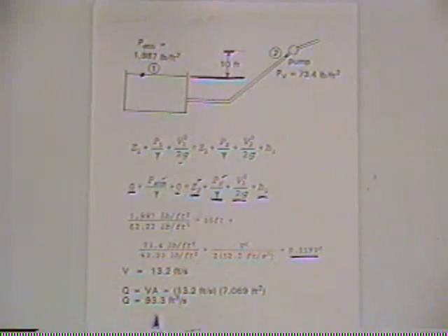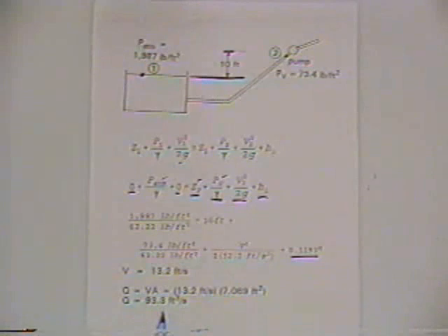So as long as we've got a discharge of 93.3 cubic feet per second or less, we don't anticipate vaporization and associated cavitation to be a problem, but if the discharge got greater than this, it would be a problem. And of course, if the discharge got even greater, you'd reach the other limit. There is a physical lower limit of dropping all the way to absolute zero pressure, which you could never get to. Now, let's work this problem all over again.